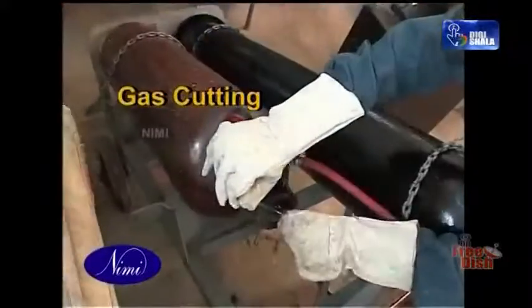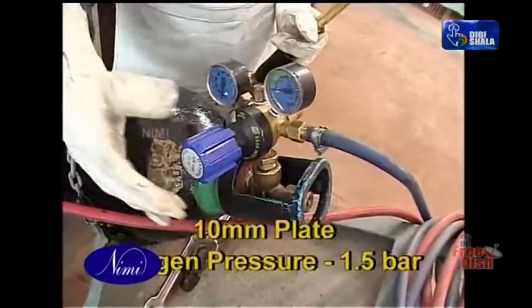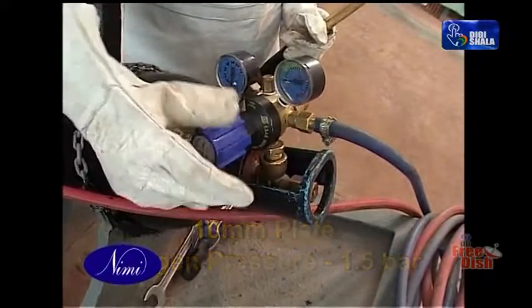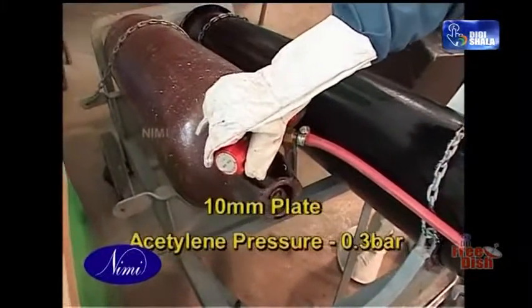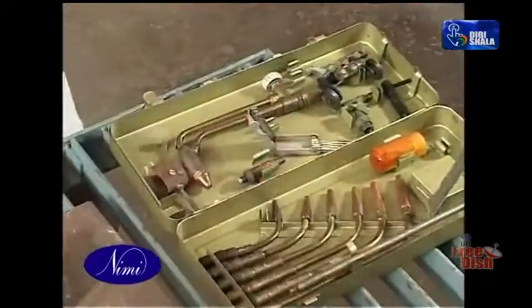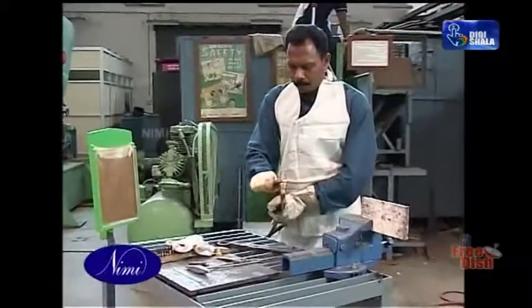Gas cutting. As the plate thickness is 10 mm, adjust the oxygen regulator knob to set the pressure gauge reading as 1.5 bar. Similarly, set the acetylene pressure to 0.3 bar. Select the nozzle size of 1.2 mm and mount it on the blowtorch.